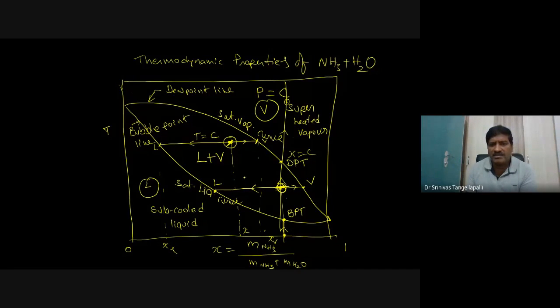But the temperature is constant. Here the temperature is constant. You may say this is the boiler temperature or the separator temperature. Separation of the liquid part and vapor part takes place at a constant temperature process. You may see how mass can be calculated as per the lever rule. See this length, from the liquid to the state, is directly proportional to the vapor mass, and this length, from the state to the vapor, is directly proportional to the liquid mass, in the opposite direction as per the lever rule.